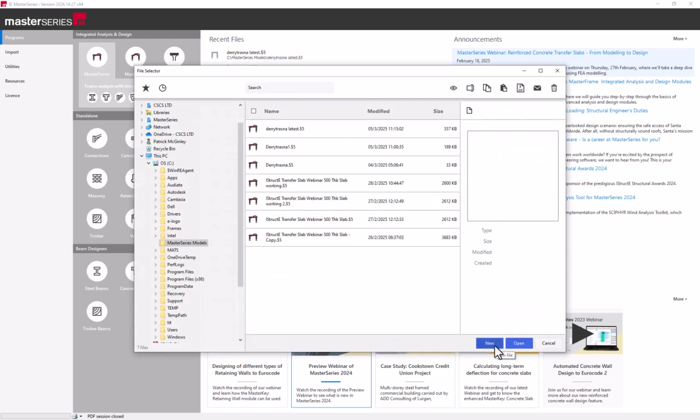I know, Ryan, we had discussed a few different options, the most critical being the FE surface vertical walls and then generating loads and being able to copy them across. So there's an alternative way of doing it as opposed to the area loading that we had been doing before. So we're going to use a slightly different way of applying these loads, but it means we can more quickly, more effectively set up our model.